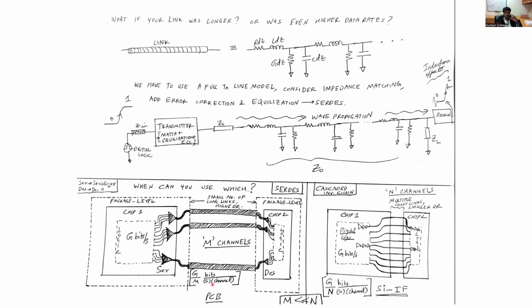So imagine a conventional package. In a conventional package, there's chip one, which at the package level could be attached to some package, for example flip chip bonded using C4 bumps to a laminate, which then could be assembled on the PCB using BGAs and so on. Similarly, you now have package one and package two connected on the PCB.